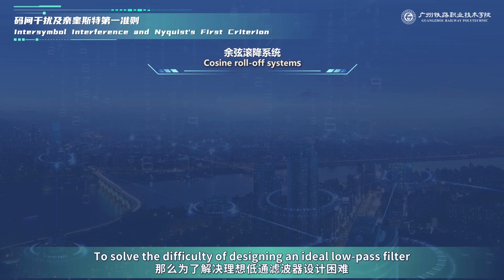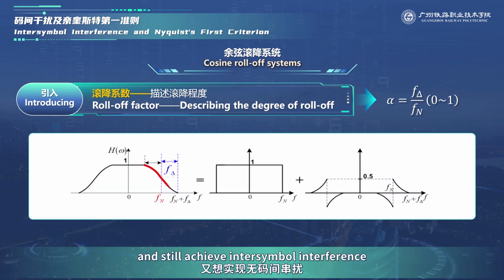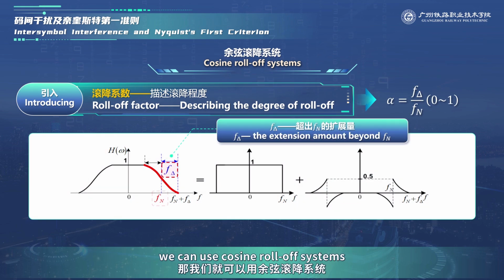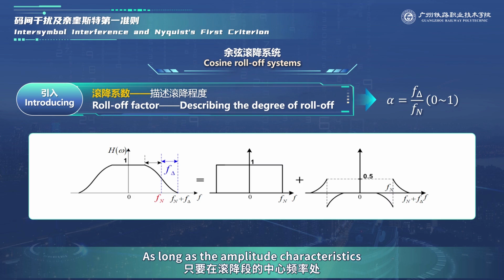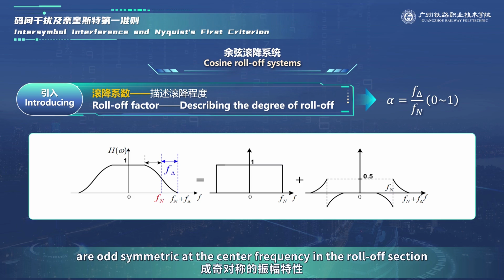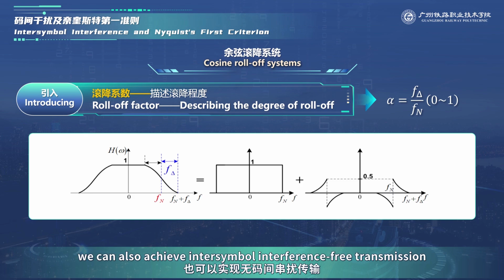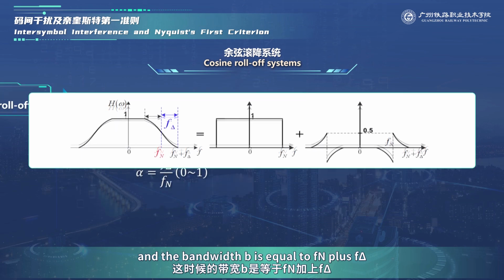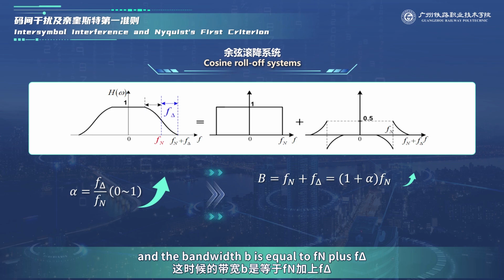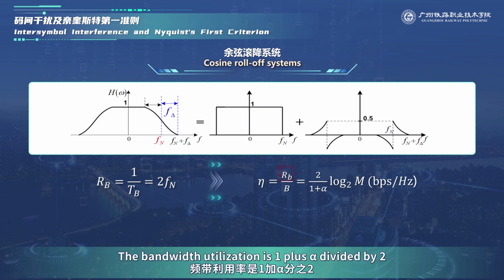To solve the difficulty of designing an ideal low-pass filter and still achieve transmission without intersymbol interference, we can use cosine roll-off systems. As long as the amplitude characteristics are odd symmetric at the center frequency in the roll-off section, we can also achieve intersymbol interference free transmission. At this time, we call alpha the roll-off factor, and the bandwidth B is equal to Fm plus F delta. The bandwidth utilization is 2 divided by (1 plus alpha).